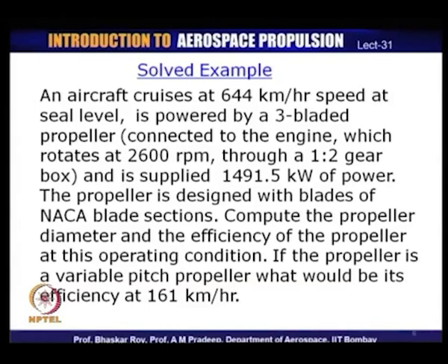It is stated that it uses the NACA blade section, which allows us to use some of the propeller characteristics of NACA aerofoil propellers, which are 3 bladed propellers. As we have seen before, every propeller should have its own characteristics or characteristic maps, and we need to use those characteristics to solve these kinds of problems.